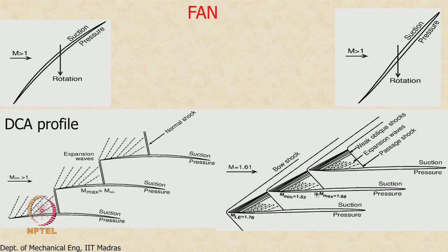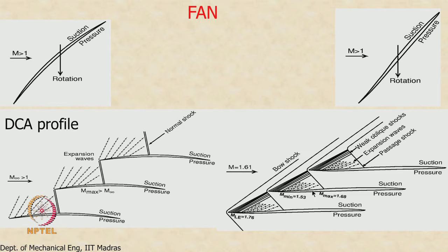So, you can see that the Mach number just at the entrance to the passage now is comparable to the free stream Mach number, but not more than that, which is the best that we can possibly do, because increasing this concave portion is not practical from a manufacturing standpoint of view.